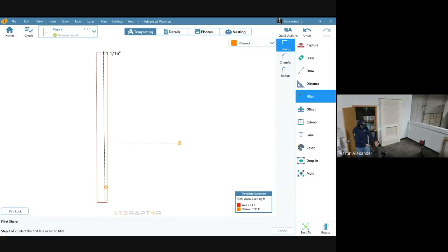That tells me that what I did right there matches the plumbness of the face of that fireplace in space right there, right? So this is a way we can verify our edits by using our lasers as well and projecting up there. Is that shimming, is my out of plumb, are those calculations correct? So now we just verified that the shimming and all that we're going to do is going to work in this situation here.